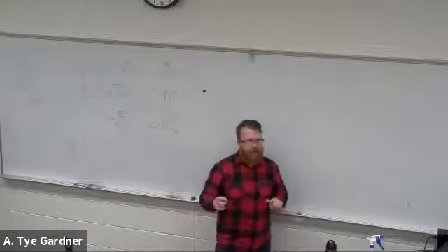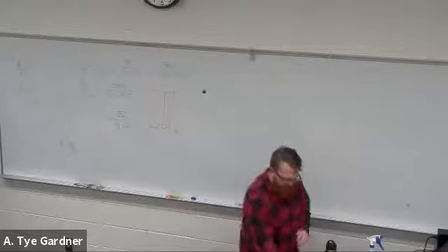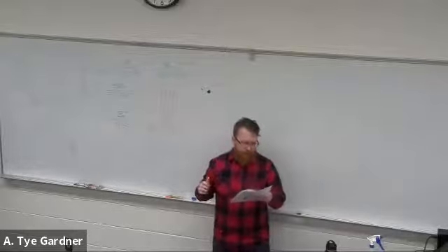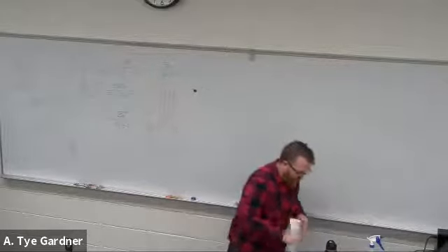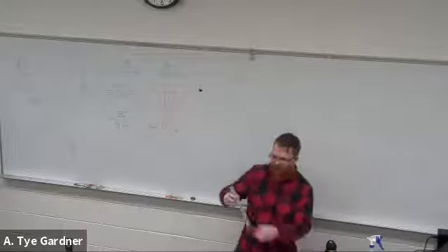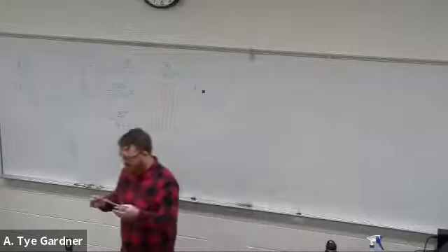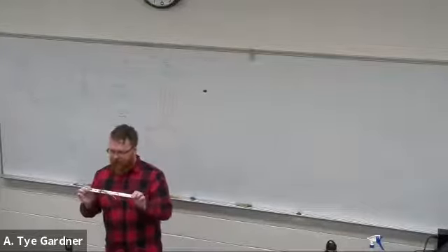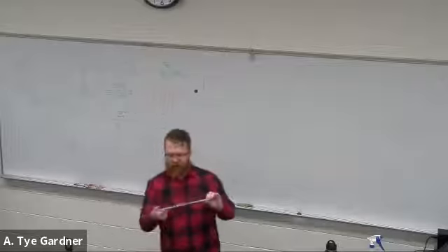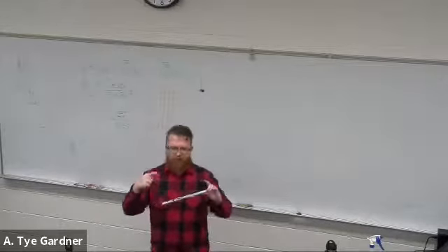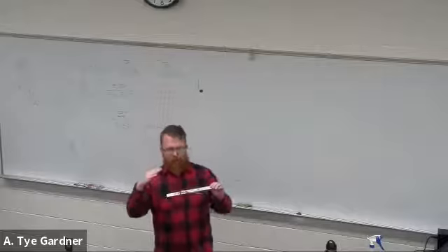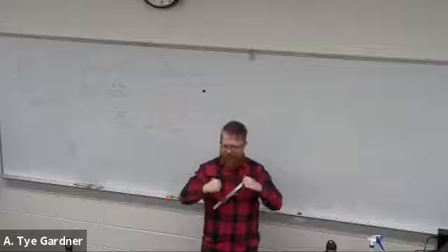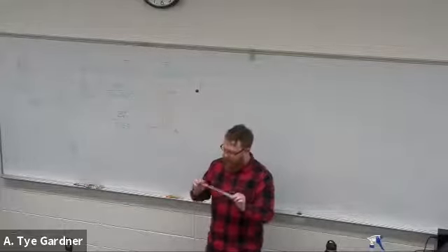It's not very big, which we'll get into magnitudes in a little bit, but this is kind of a tricky thing to measure. If you want an example of it, I actually managed to go find one. This one actually has 3 different strain gauges. What's kind of useful is if you were to put one of these on the other side, you'd have a calibration sensor, right? On one side you would measure the expansion, and on the other side you'd measure the compression, and you could calibrate them against each other.